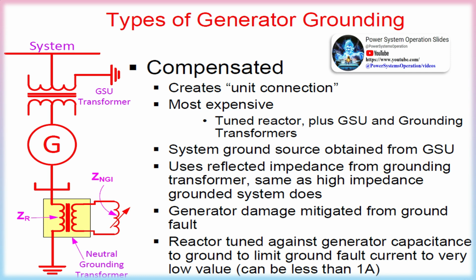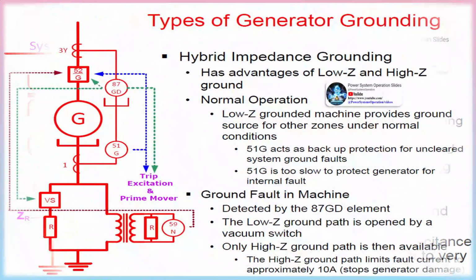It is desirable to avoid any undue stresses in the generator, and for that it is usual practice to install a surge capacitor or surge diverter or both to reduce the effects of lightning and other voltage surges on the machine. The protection schemes usually applied to the generator are discussed here below in brief.